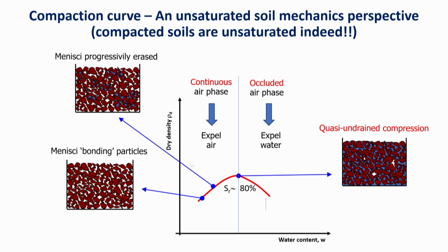This is the point when the air becomes occluded. So now the mechanism is different. The air is very easy to chase. When you compact, the permeability of air is very high, so the air is moving so fast that you're not even thinking that there is a consolidation process. Technically there is, because the air is taking some time to flow out, but it's so fast that you don't think about it. Now you need to chase the water.